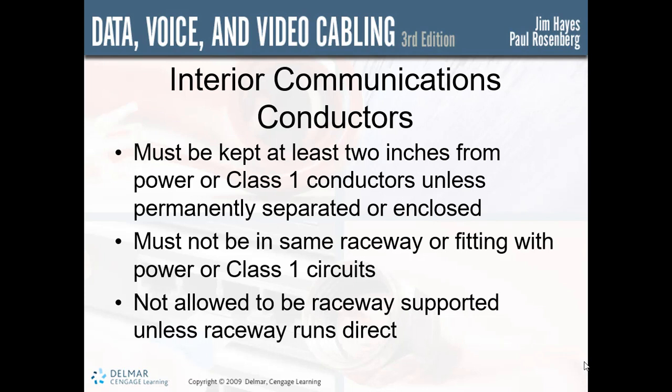Communication cables are allowed in the same raceway, box, or cable with any of the following: Class 2 or Class 3 remote control, power-limited fire protective signaling systems, conductive or non-conductive fiber optic cabling, or a community antenna or television system. You'll notice in all of those, we are not keeping any of our communication cables in the same raceway or conduits as electrical power.